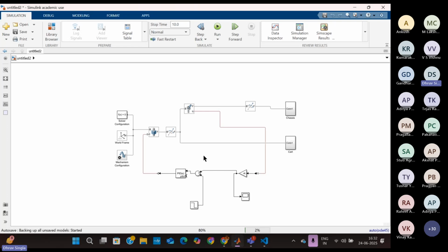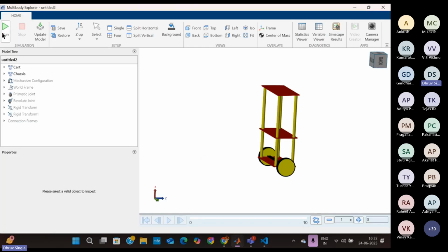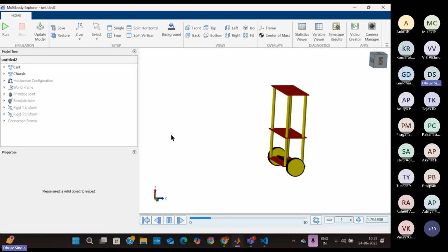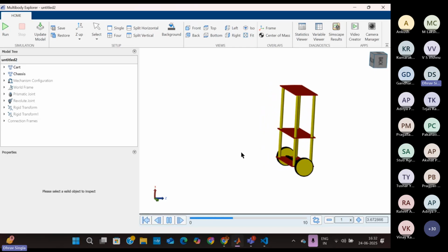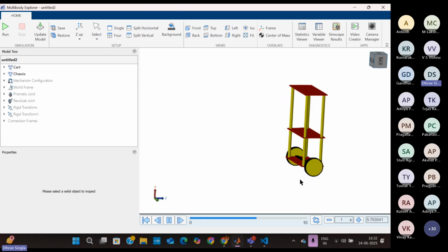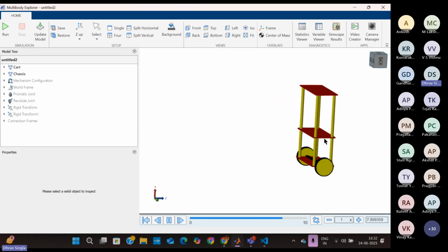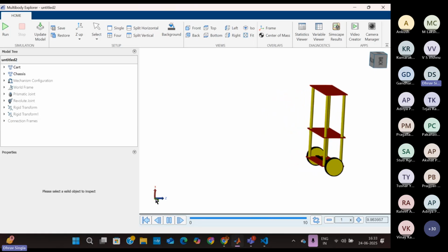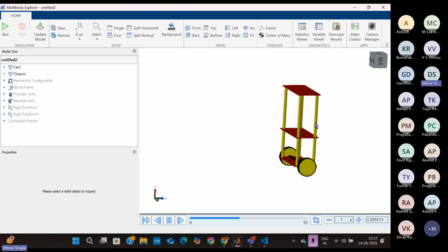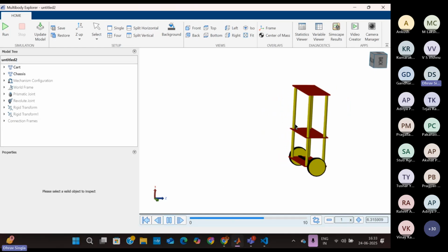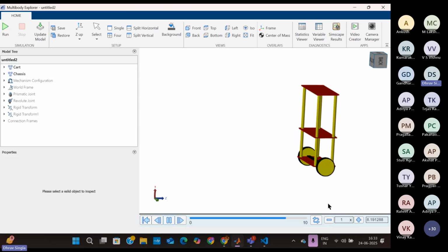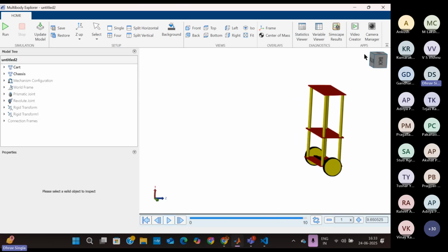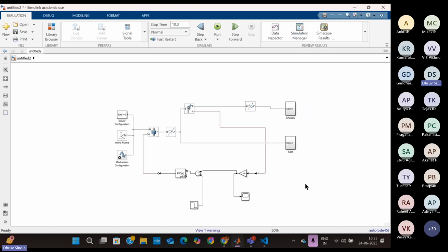But if we go back and see our simulation again, the same problem that I discussed in the slide is coming. If we see the orientation, the tilt error has been removed, but our board is still translating in the axis. As we see over here, the tilt is now fixed, it's at equilibrium, but the boat is still moving in the z-axis. So for that, we need to introduce a translational feedback loop to our control system.